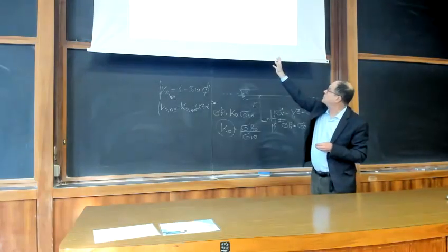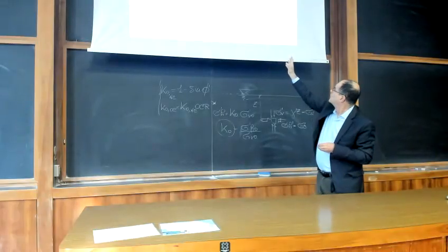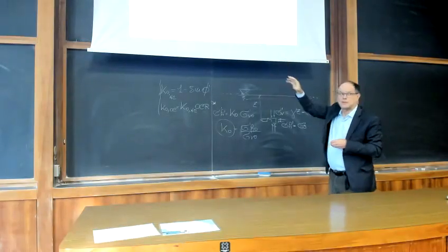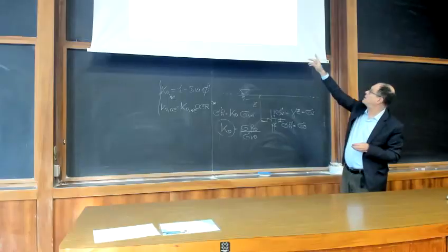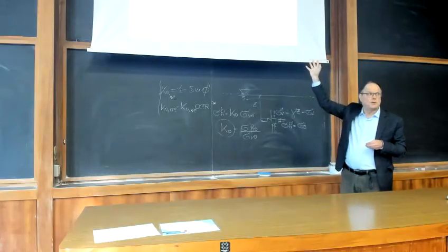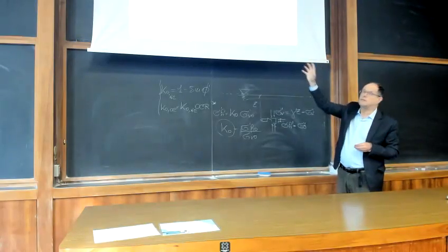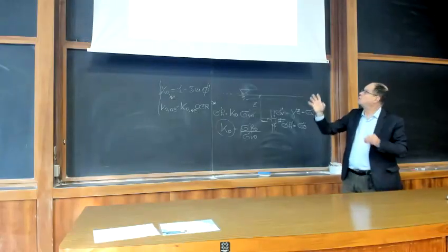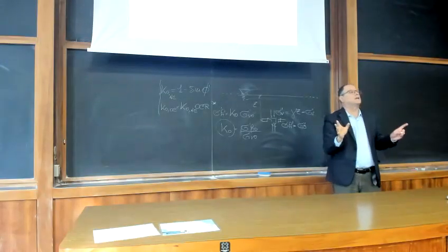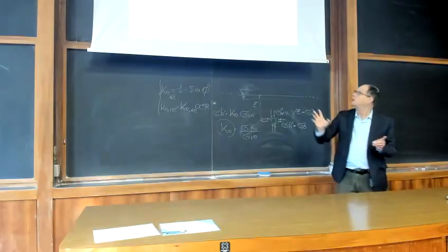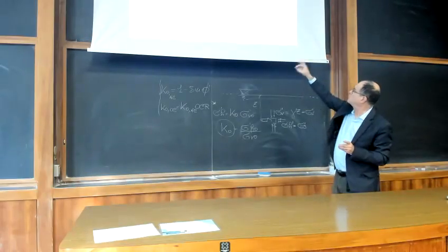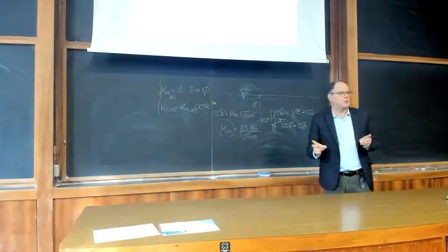One with the horizontal stress smaller than the vertical stress, the other one with a horizontal stress greater than the vertical stress. So you have two circles statically determined, only two, that are tangent to the line and go through your vertical stress.